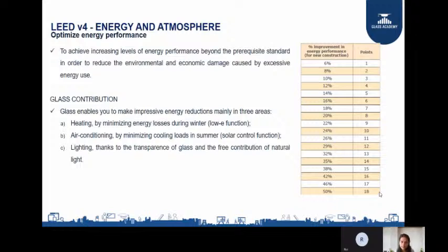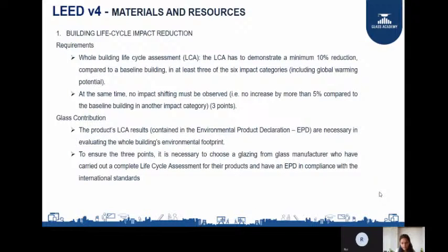So in India, basically, widely we have three green rating systems which people generally follow. One is LEED, Leadership in Energy and Environmental Design. Then we have IGBC, Indian Green Building Council, and then we have GRIHA, Green Rating for Integrated Habitat Assessment. Basically, these are the three green rating systems. In addition to that, we also have ECBC, Energy Conservation Building Code, and the NBC, National Building Code, which are a kind of guide which will give you guidelines in terms of energy consumption.